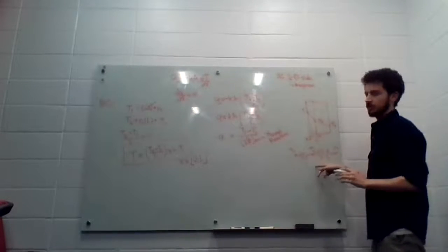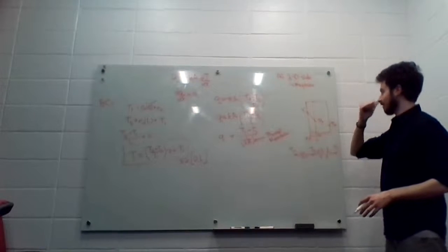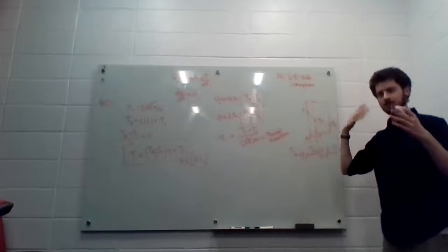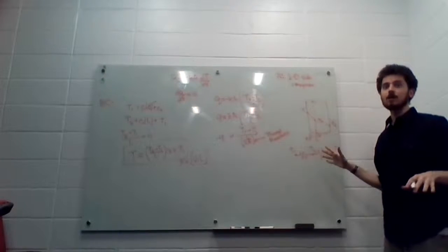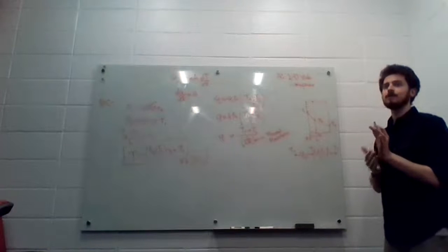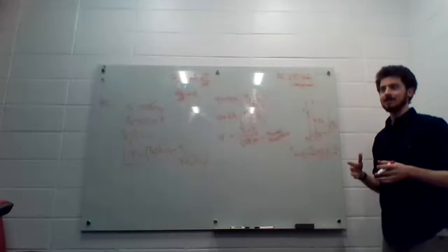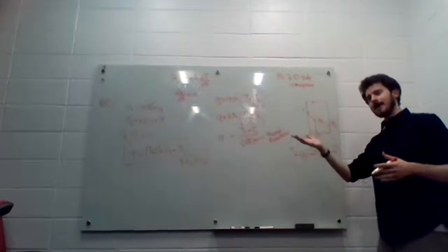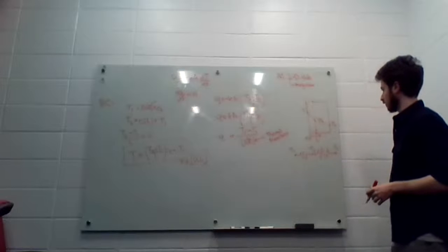This thermal circuit that we're drawing right now is based on a one-dimensional slab, no internal heat generation, all these things. When you start adding those things in, this goes out the window. So down the line, don't try to model internal heat generation as a resistance while also adding heat in. That thermal resistance only applies when there's no internal heat generation.